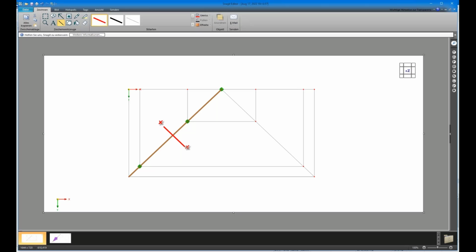And now we can measure our tributary length by measuring this distance, depending on the projection plane and so on. But when we are in the projected area, we can use this value directly. And the tributary area in this case is then exactly here, this purple highlighted area.